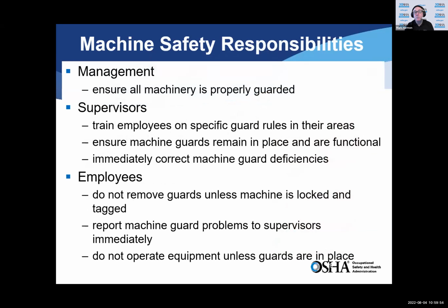Machine safety responsibilities. Again, we always point to, okay, management, right? The company officials should ensure that all machinery is properly guarded. Very good bullet point. Supervisors work for the company, but they should train the employees on specific guarding rules in their area, ensure that the guards remain in place and are functional, and immediately correct machine guarding deficiencies.